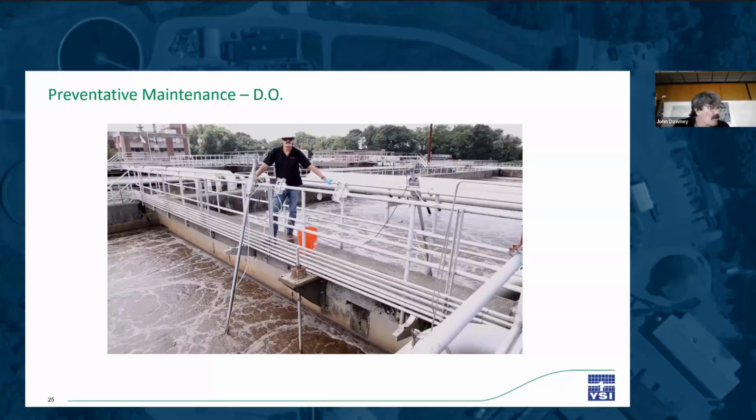The network sensor will hold the calibration for its entire service life. It also has a T90, that is a time to reach 90% of the actual parameter concentration, of about 3 minutes. The handheld device we are using must be calibrated once a week. However, it's much more reactive and it reaches a stable state for measurement in about 10 seconds. To accommodate the difference in function, I will immerse a handheld sensor next to the network sensor to be assessed, then walk back to the control room to get a display. The extra minute or two before starting the comparison measurement usually saves multiple readings, and acceptable results, for me anyway, are within a quarter part per million.